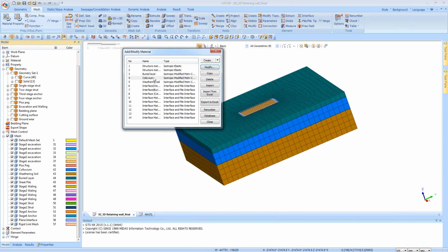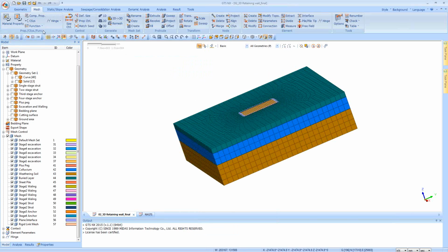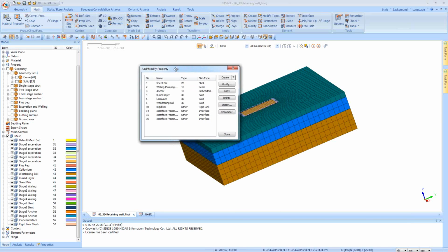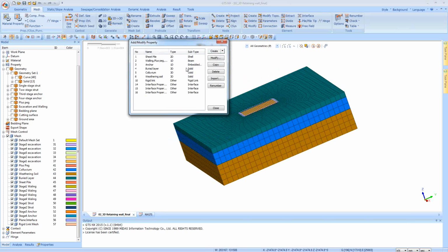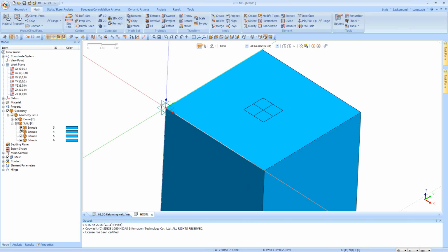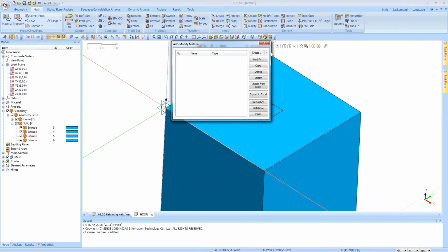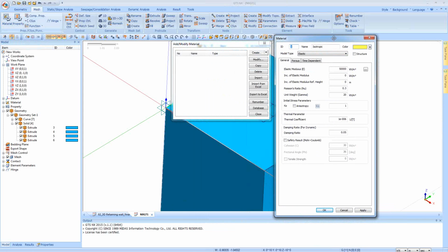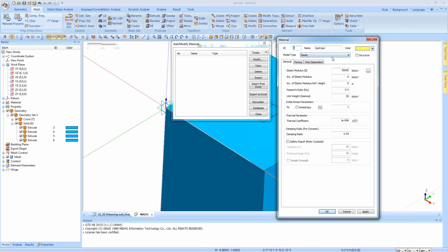Then after defining all the material properties, you need to define the property. And this is basically what kind of element you are going to assign it to, for example, 2D, 1D. So what I will do is show this step quickly. For example, these are our solids. So material, let's say isotropic. I'm just trying to make you familiar with the general workflow.